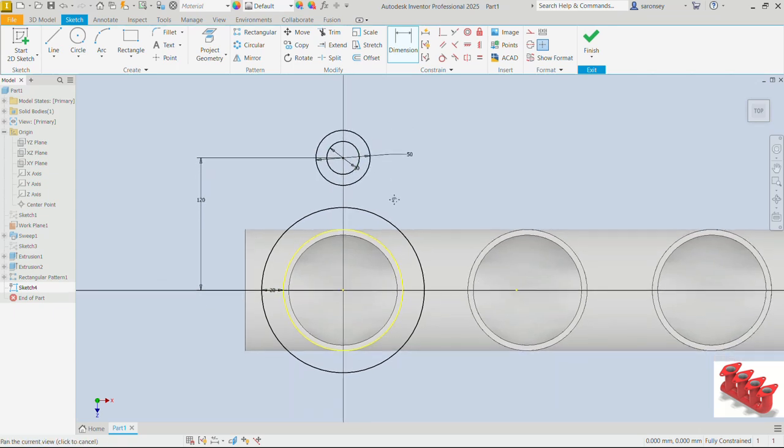Let's enter that. Next, I will pick the line command. Let me draw a line to connect this to that. Make sure you are not locking onto this very point here. That divides the circles into 2, but yeah, anyway here should be fine. Then apply the tangential relationship between this bigger circle and that one, also between this and that.